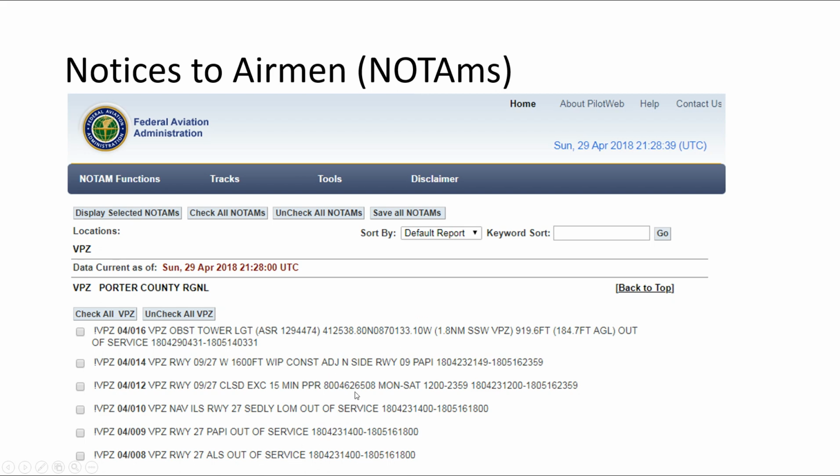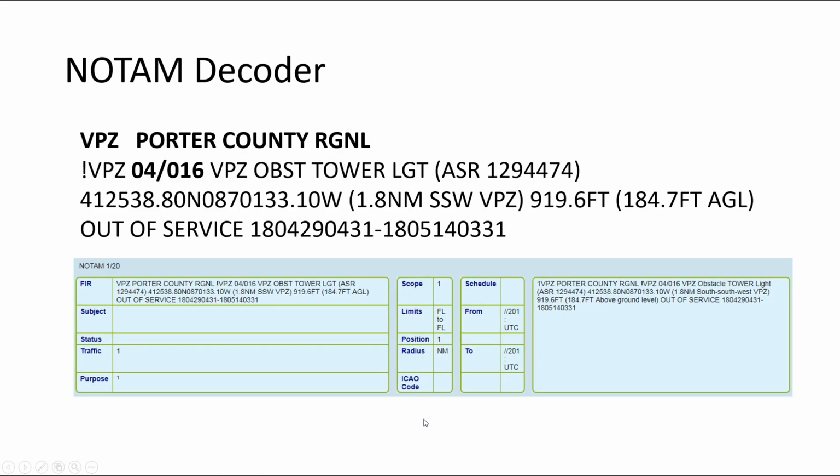And sometimes, if a taxiway is not in use and has been closed, like right now they're parking jets on taxiways all over the place, they'll put out a notice to airmen: hey, taxiway Alpha 4 is closed, so don't try to use it. Here, the PAPI is out of service. We know what that is, that's the slope guidance lights. Theirs broke, so they're out of service. So that's another thing that you can, as a pilot, check out.